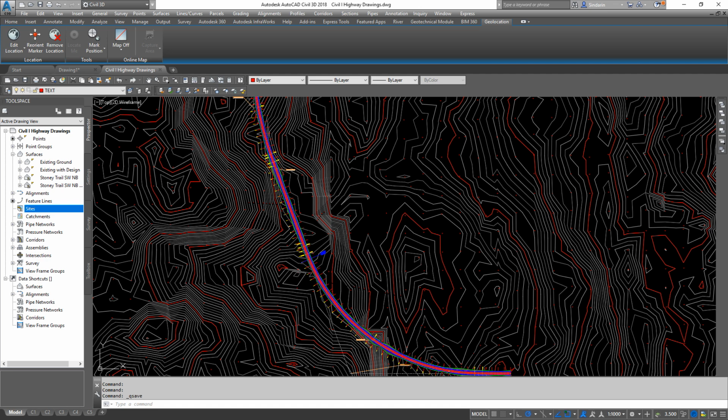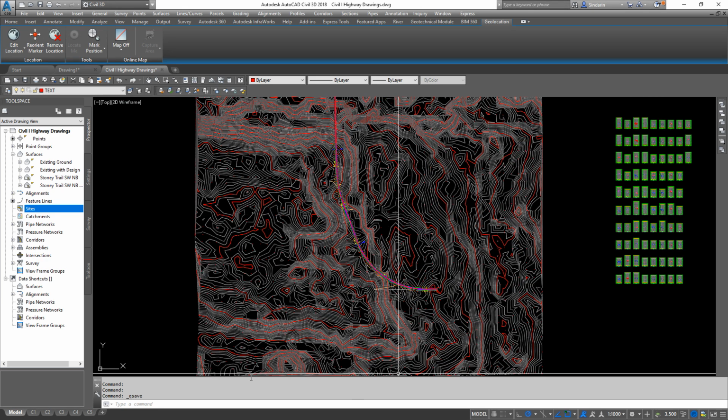We could figure out the contributing area, so how much area of land is flowing into our pond, what different kinds of soil are on the ground, if it's grass, if it's asphalt, if it's gravel, etc. Each one has a different number for how much water will basically soak in, how much will go to the pond. Now, again, with the intensity data, with the area, with the imperviousness of the soil, we can figure out how much volume our pond actually needs to hold.